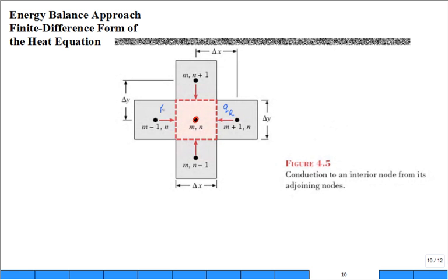I could have flow in from the left, Q from the top, Q from the bottom. And now I just work out the algebra. And it is good to develop a simple rule: everything goes into the node of interest that I'm trying to write an energy balance for. So don't try and be tricky and say, well, I think it's hot over here and cold over here, and so this arrow's coming in, but this arrow's going out. It's better just to say all in.